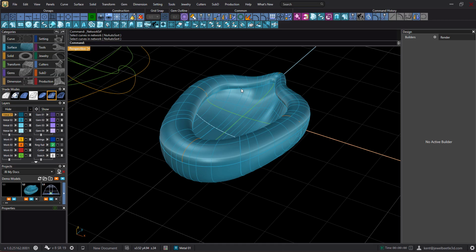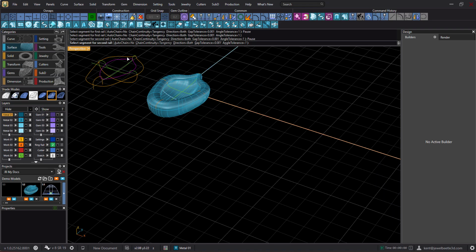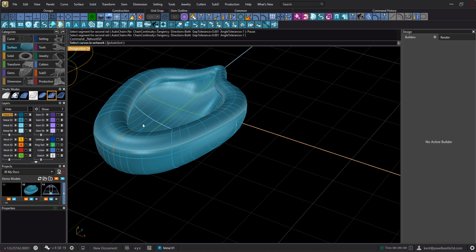Now, in sweep 2, if we start sweep 2, you notice it says chain edges, right? And we're all used to that, or at least people that have run this before. So if you start it, you can say chain edges, and then you can pick multiple sections to make one edge. Okay. If I go ahead and start this, I have no chain edges. I can't make a selection all the way around to make one edge.